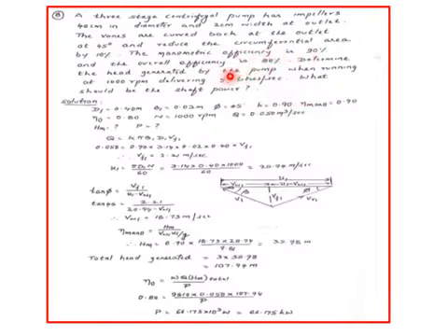We have to find the head generated, HM, and also what should be the shaft power. The pump is running at 1000 rpm and delivers 50 liters per second, so Q is 0.05 meter cube per second. Since Q is given, we can use Q equals K pi B1 D1 Vf1. Here Q, K, B1 and D1 are all known, so we can find Vf1, which equals 2.21 meter per second.